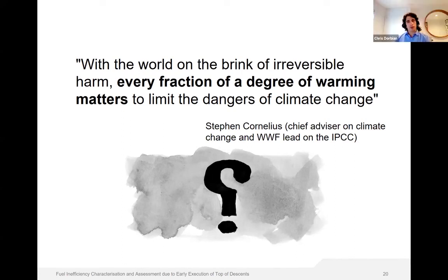Another question from the audience about the ATC role. How can ATC practically respect a top of descent if it's dependent on so many factors, for example cost index, mass, wind, as you talked about, and those factors aren't just aircraft, airline and flight specific, but can change over time depending on things like the price of fuel and how that influences cost index?